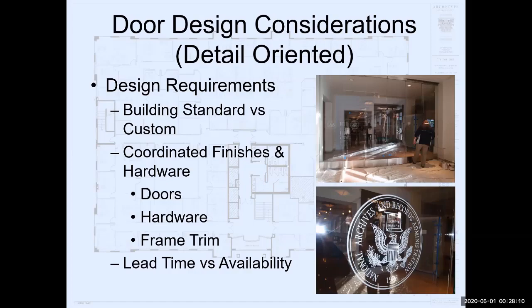So I want you to think about that and understand that anytime we get involved in those unique applications, we have to be thoughtful of their installation, their constructability, and how they work with that door. You need to work pretty closely with the manufacturer to make sure you understand how this best works. And be advised that sometimes these doors aren't on the shelf. It takes time to fabricate them, and their availability might be limited. So you have to think about that as well.